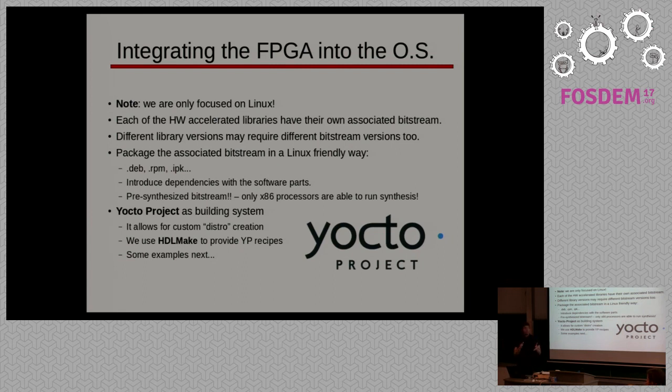We are using the Yocto project as the building system, so that everything, including the different bit streams associated to the libraries, is managed. And we use HDL-make in order to integrate the bit stream synthesis inside the operating system generation.